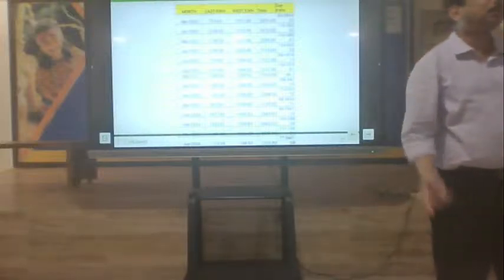Basically it will be checking the output, and based on the output it will be setting the input limits. There is a program that is being done there. That is what we call the MPPT tracker algorithm. To write that program, you need to understand the basics of how this is happening. Only then can you write the program. So how do I change my switching frequency, the on and off timing, based on the output? Each time I have to estimate what my input is and what my output is.